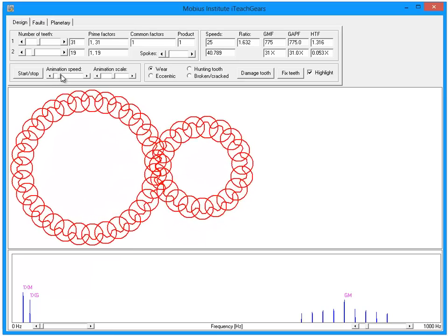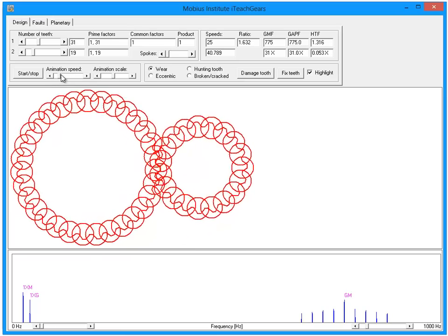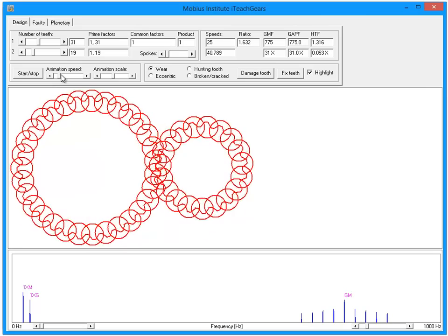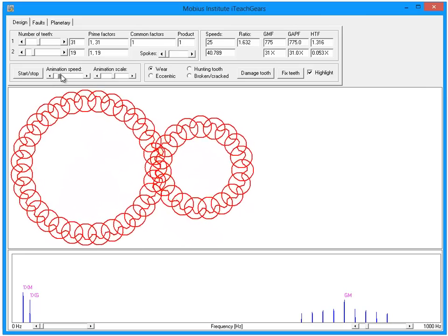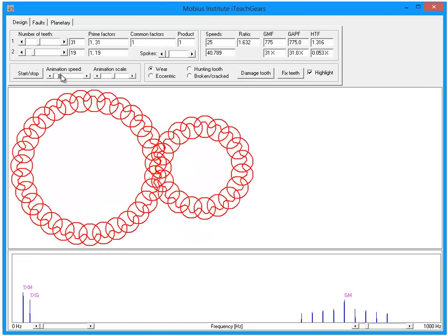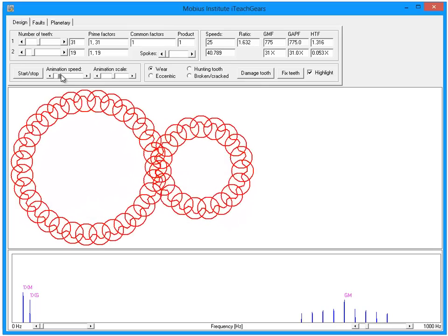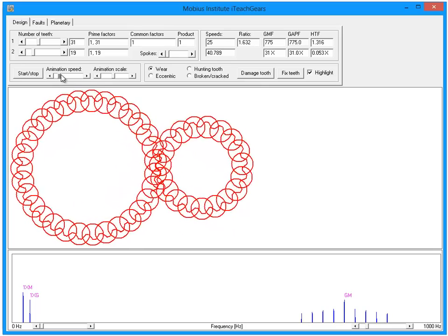Same could be true if, when the gearbox was transported or installed or whatever, two mating teeth may just damage each other, and as the gearbox rotates, that damage, that imperfection, has the potential to spread around all the gears.